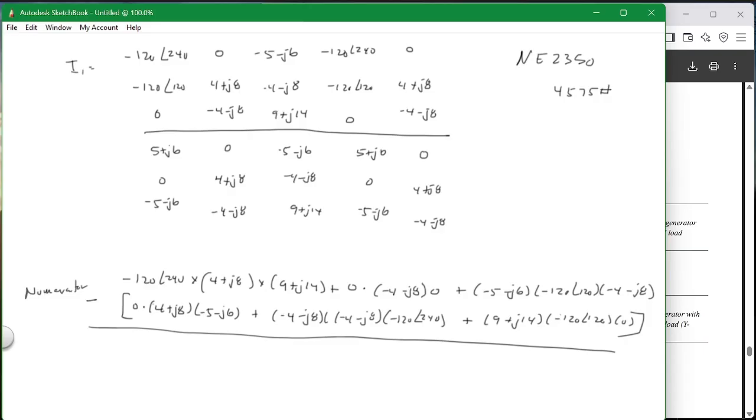That's why in my drawing, I put it going to a relay, which then has normally open and normally closed contacts, so that either way, you can pick one and choose which one you want. I did that on purpose, because you might get the wrong one, or you might not get it wired right, and with a relay, you can always choose which way you want to go.